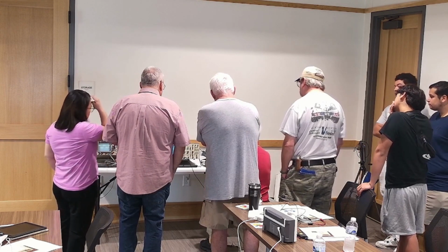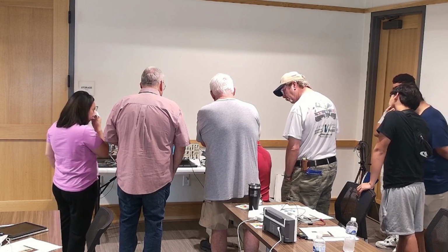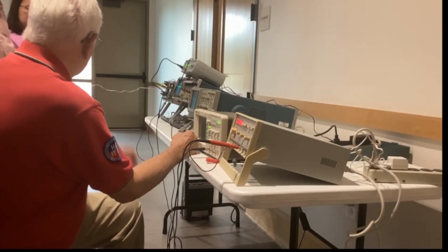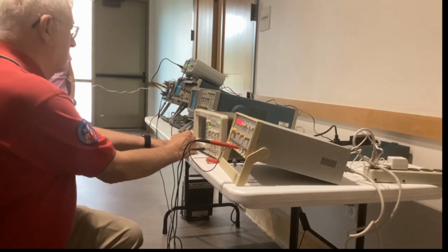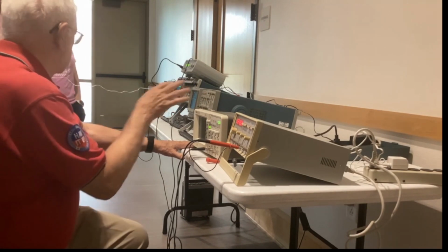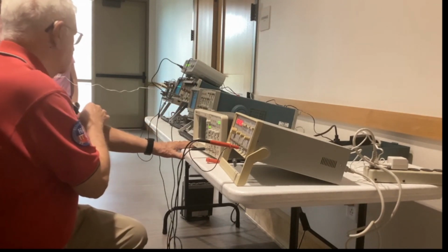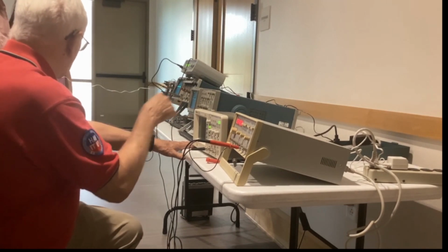Yes. You can also use a scope to see the output of your transmitter to see how pure your waveform is coming out of your transmitter. It takes another little piece of equipment to do that, to basically downshift it where the scope can see it. The scopes can't see anything that fast, but with a downshift you can actually see what your voice looks like in waveforms as it comes out.